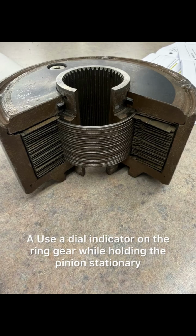16. What adjustment moves gear contact toward the toe of the gear? A. Decreased pinion shim thickness to move pinion closer. 17. What adjustment moves gear contact toward the heel of the gear? A. Increased pinion shim thickness to move pinion away. 18. What does an outplay on the pinion indicate? A. Worn pinion bearings or loose pinion nut.